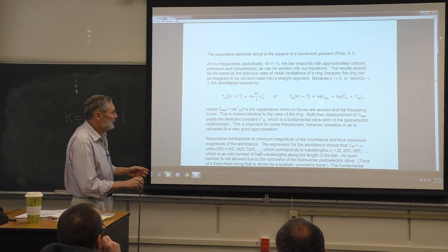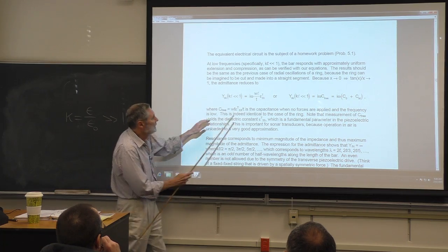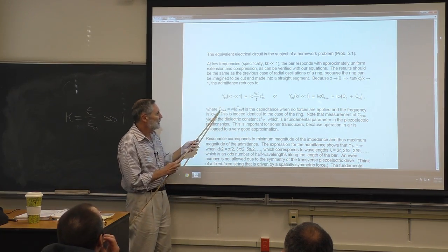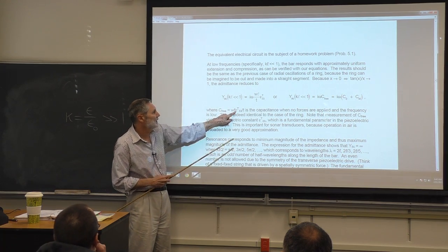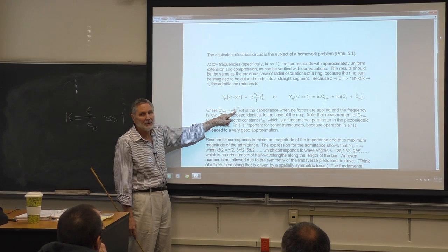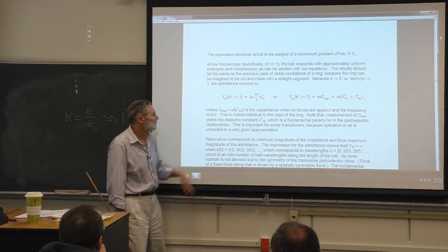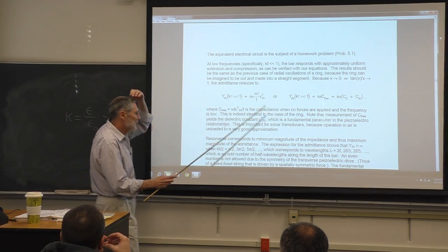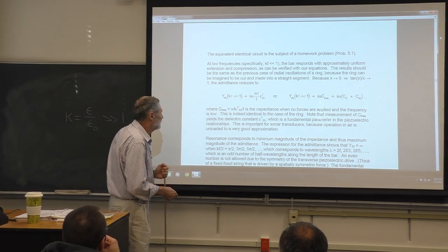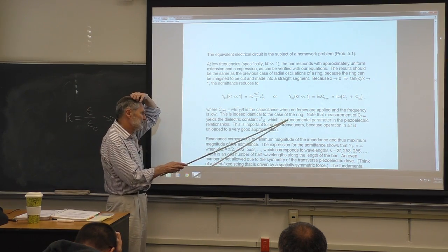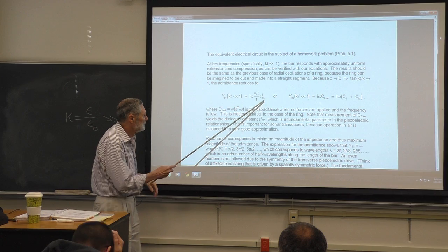And as you know from the lab, the reason this is important is that the free capacitance is given by this expression, so by measuring the free capacitance, we can get at epsilon 3,3 for constant stress. That's important. So it can be shown that it does correctly reduce. That's why this is important.